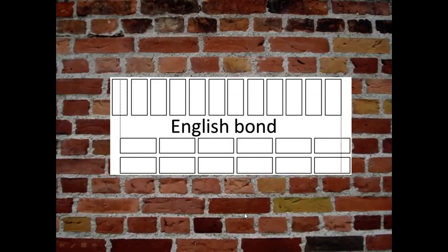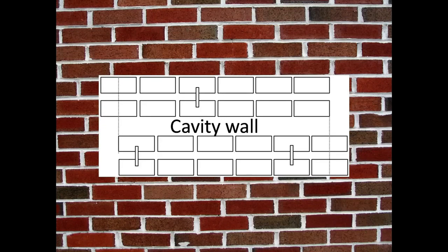Just to confuse the issue, I would have said to you that every time you see a wall that's just a series of stretchers, not headers, it's going to be a thin wall, isn't it? It's going to be a 4-inch wall, 4.5-inch wall. It's just going to be one thin wall, and therefore it will not be load bearing. It'll just be a facade, something that's keeping the rain and water out, and the floors are actually being carried by some other system, concrete or steel, what have you.